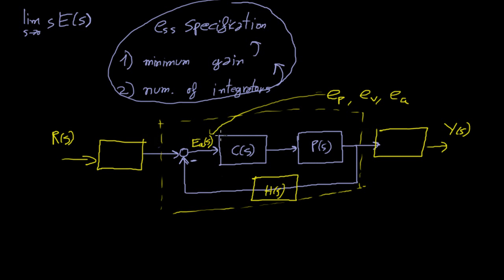Because in each situation, you will think, okay, what are they asking me for? On what signal should I apply the final value theorem? Is the acting error the same as the actual error in my system? What will I achieve if I raise the loop's type? Should I introduce some extra element out of the loop to achieve good tracking?